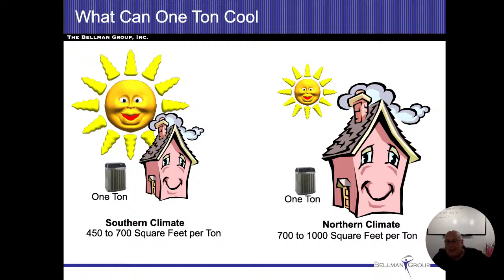So we don't divide everything up and say, well, wait a minute, you've got 5 tons now for a 1,500 square foot home. What I do know is that for the most part, my second floor air conditioning and heating system is going to be running in the summertime more. Heat is going to rise, and I have an open staircase. So that's the one that's going to be doing most of the work. The first floor one would hardly run at all, but if the heat does come in there, it does actually run.